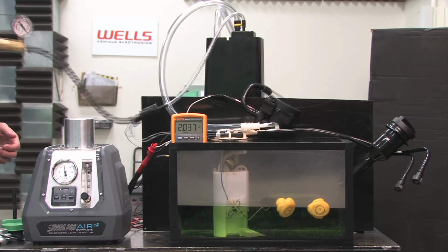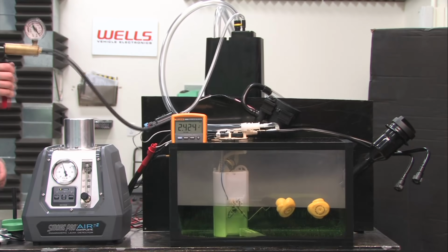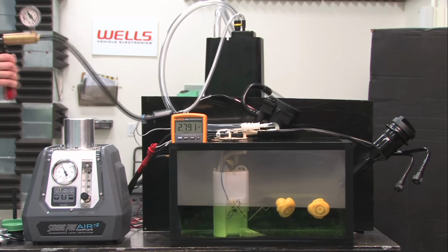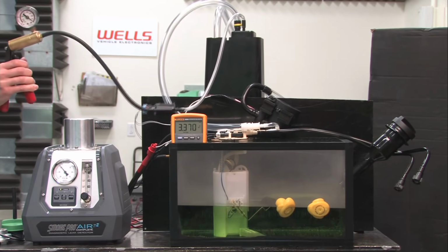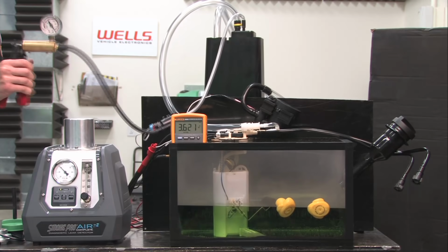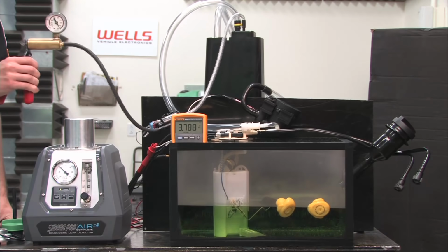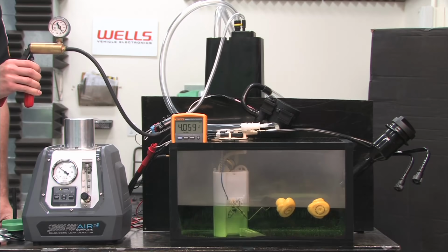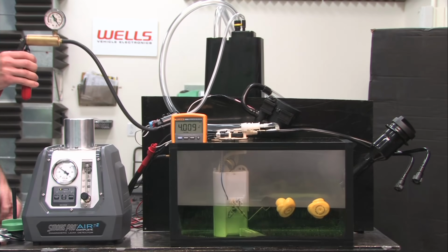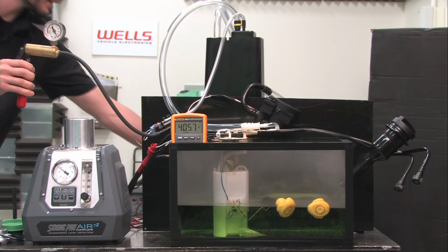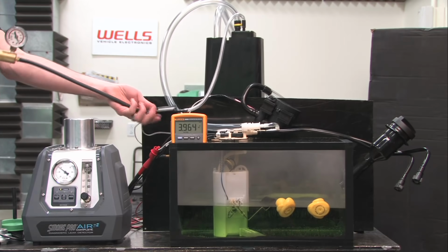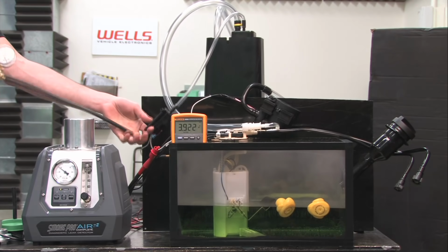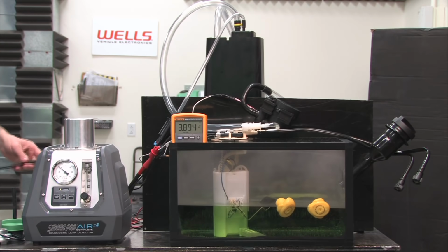And before my hand cramps up, we should see this thing drawing vacuum. And you can see vacuum is being applied and our voltage is going up. So let's say the threshold in the computer for this vehicle is, let's just call it 4 volts. So I'm going to draw this thing to a 4 volt mark, okay? Right there, we are going to leave it sit there, and I'm going to close up the purge. So I just disconnected, the purge is now closed. I'm going to pull the vacuum pump off of here, and our front door and back door are now closed.